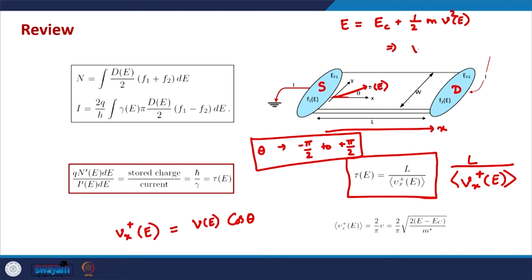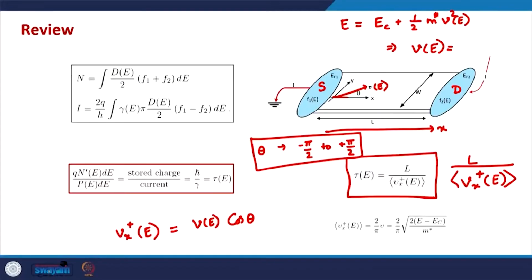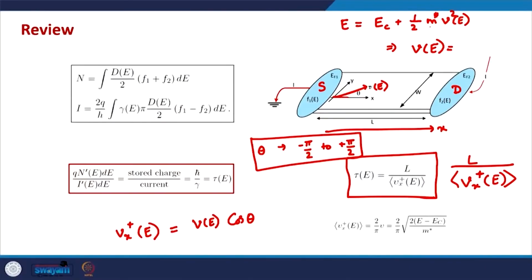So this Ve is equal to... please keep in mind that generally when we treat the electron as a classical particle, we need to have the parabolic band structure, which means the E-k relationship should be a parabolic relation. E should be equal to EC plus h bar square k square divided by 2m star, and instead of the electron mass, we need to have the effective mass.